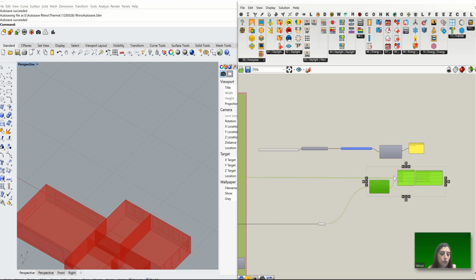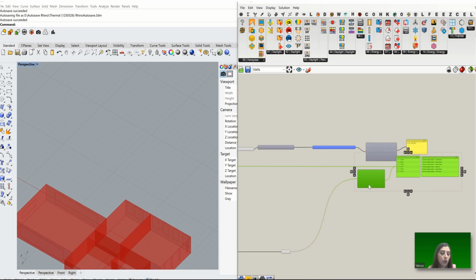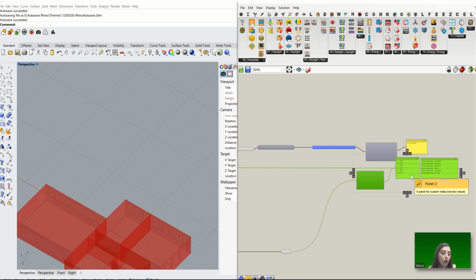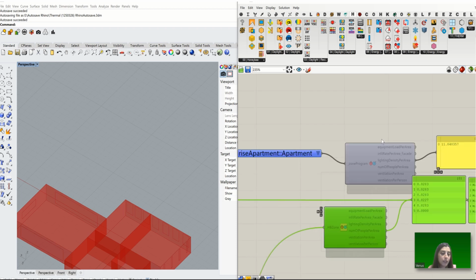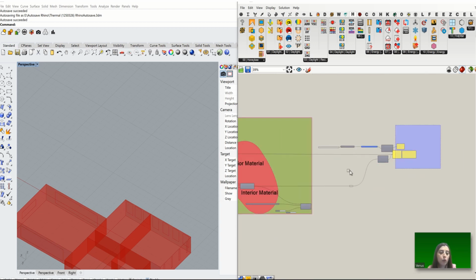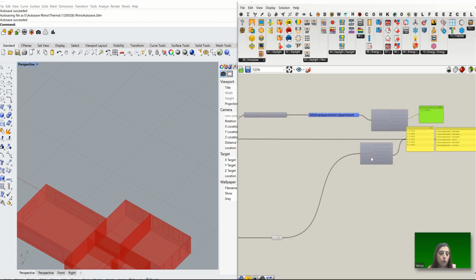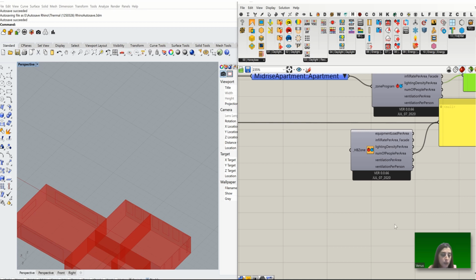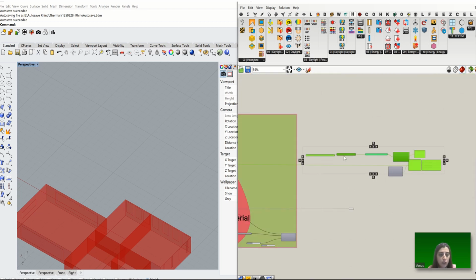You can use this two-way to find what the number is and what value Honeybee is using for your project by default. But we are not planning to use this number, and we want to manually add our own number. So please disconnect this HVAC zone, the HB zones, and also the numbers.